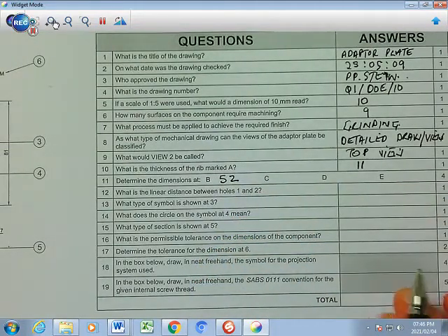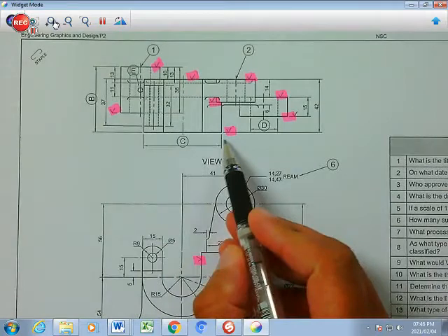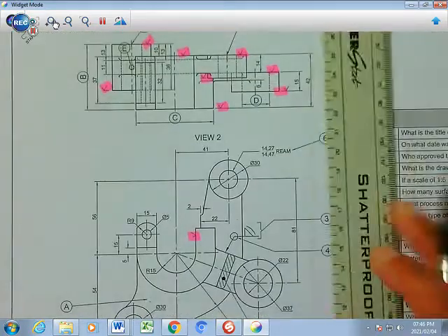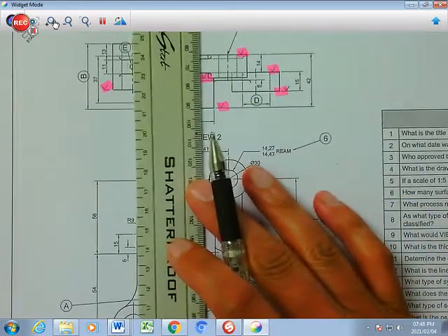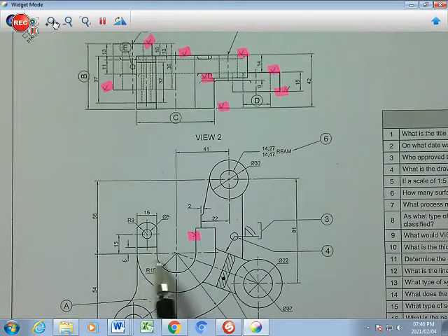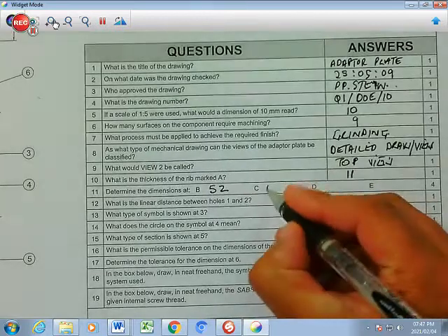And if you go to C, C refers to this part over here. You're not going to find the answer here, but if you line it up there, you will see it is this component here. From that center till there is 15 radius. From the center till here is 15, plus another 15 till there. That's 15 and 15, that's 30. And if you go this side 15 and 15, then altogether it's going to give you 60. You go to C and you fill in 60.